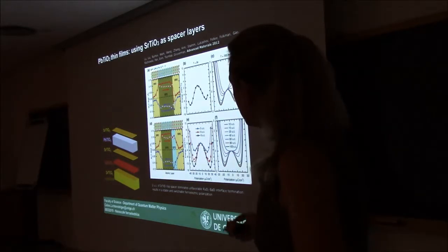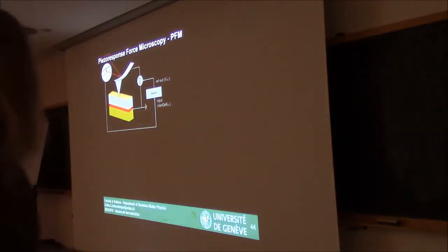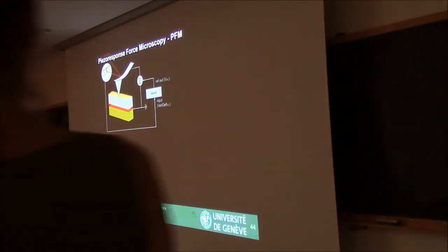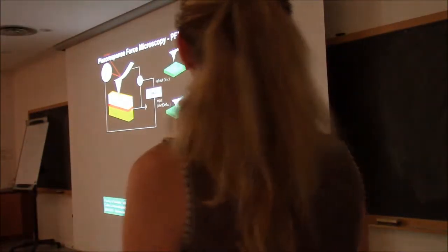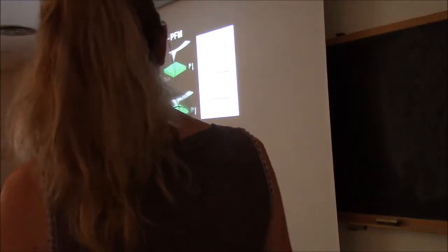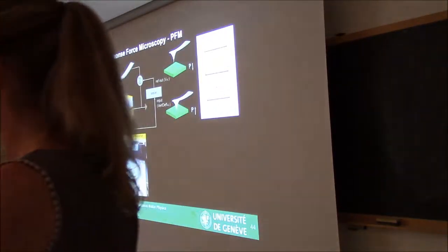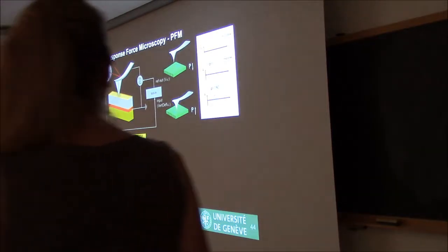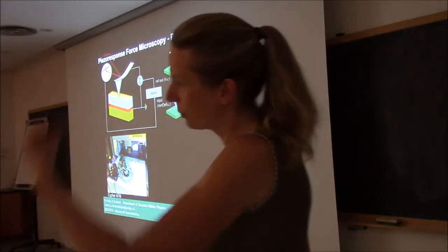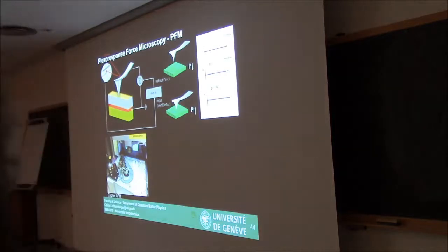So we did that with the idea of being able to change the thickness of the STO and the PTO, and see what happens. We use PFM, and in principle you know everything about PFM now, hopefully. Just to remind you, you come with the tip of the AFM, you apply voltage, you see how the material is vibrating, either in phase or out of phase, you record the signal, and you know below the tip what the orientation of the polarization is.